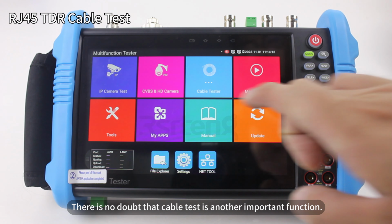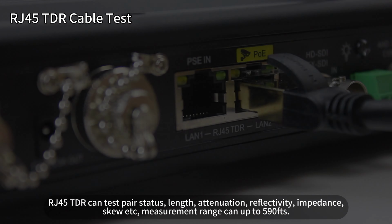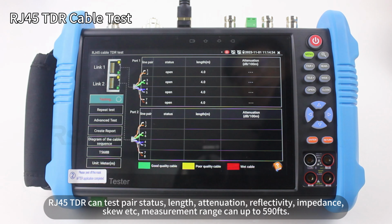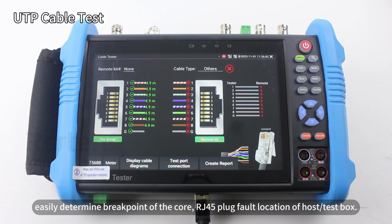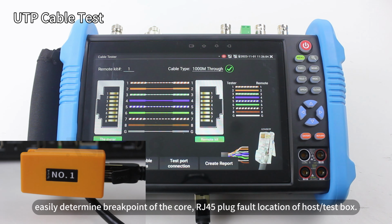There is no doubt the cable test is another important function. RJ45 TDR can test pair status, length, attenuation, reflectivity, impedance, skew, etc. Measurement range can be up to 590 feet. UTP cable testers can easily show cable connection status on the screen, easily determining the breakpoint of the core and RJ45 plug fault, with the location of the host by test box.